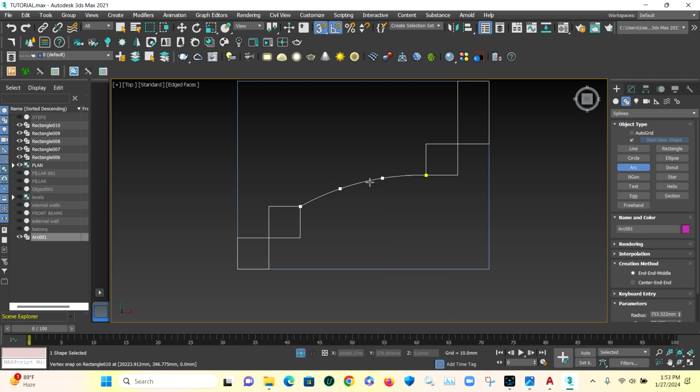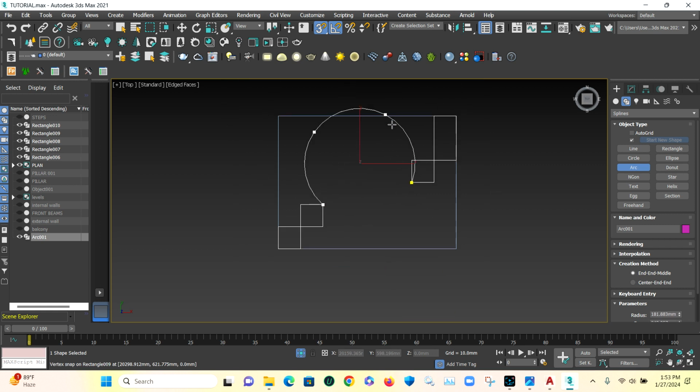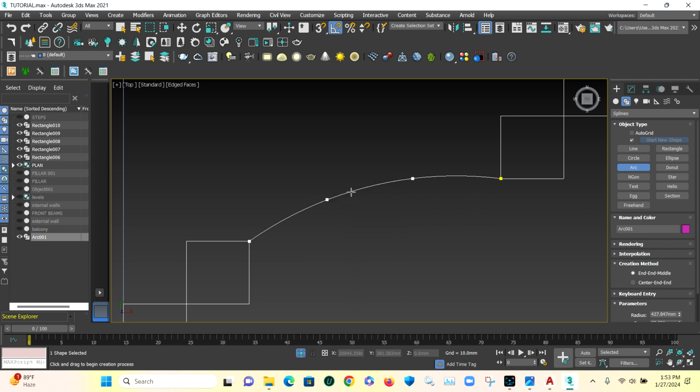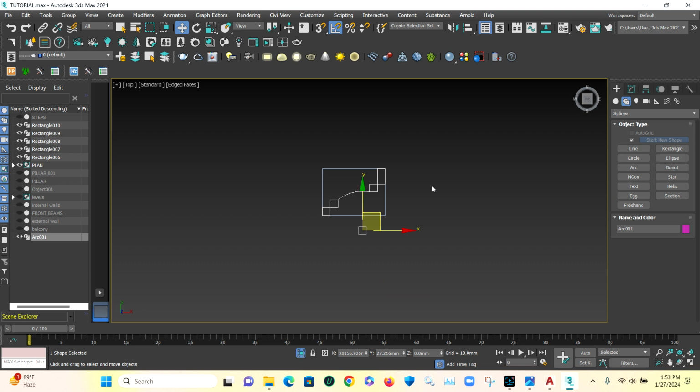Now you just move your mouse. It will go with you till you achieve what you want to achieve. And while doing that, if snap becomes a problem, let's say you have other things on this screen and it's snapping, then press S on your keyboard to turn snap off while you achieve what you want. Once you have achieved it, you left click, and that is it.